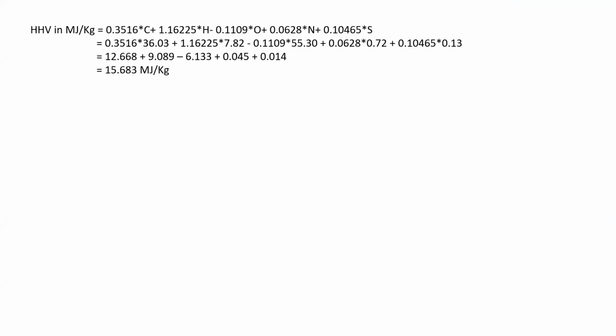Okay, and one more thing, Venkatesan, you were asking whether gasification is an endothermic or exothermic process. Gasification is an endothermic process because first we have to provide very high temperature inside the gasifiers. Heat is provided for heating the reactors, and also steam and oxygen are applied. So gasification is an endothermic process. Pyrolysis is also endothermic, but incineration is an exothermic process.